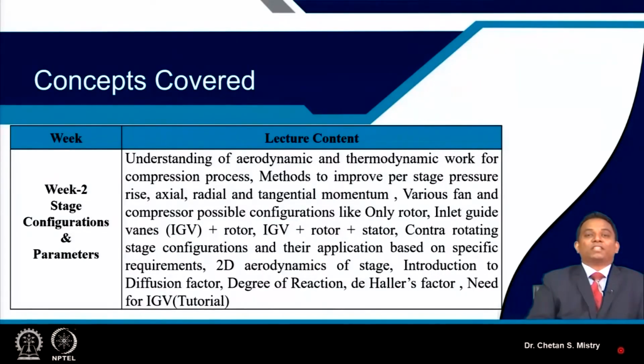We considered special applications using a single rotor, or only a rotor with inlet guide vanes, and the rotor configuration. We have discussed the rotor and stator configuration. We have discussed the inlet guide vane, rotor and outlet guide vane configuration, which is what we call the 1.5 stage configuration.